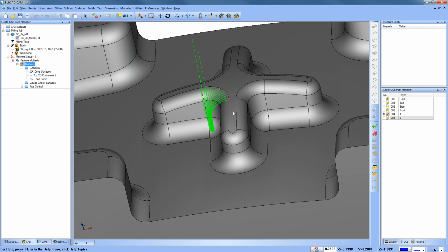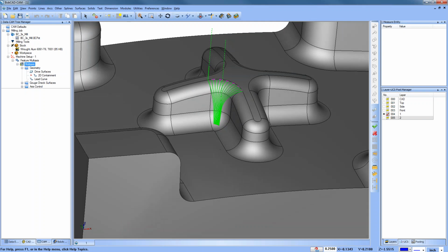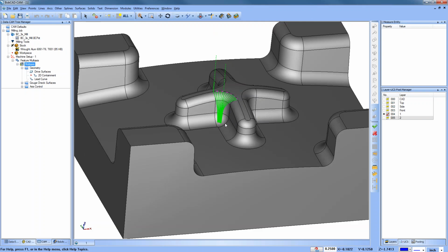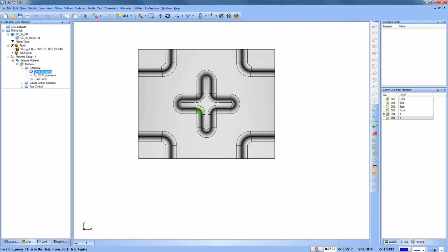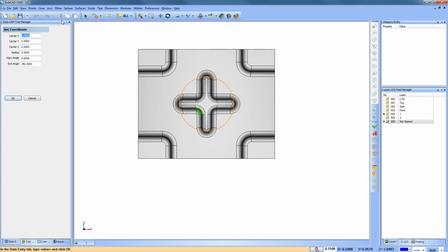All right, very good. So this is cuts along a curve. You have your lead curve, and you're going to get perpendicular toolpath to that lead curve following along your drive surface. Okay, if there's any questions about that, go ahead and ask. Otherwise, we're going to move on to the next curve-based toolpath. So what I'm going to do is draw some geometry here. Let's go with 3.